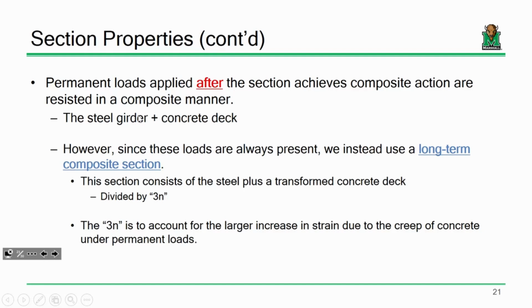Now, if you've had pre-stressed concrete, you know as well as I do that concrete is a material whose properties change over time. Concrete undergoes things like creep and shrinkage and what have you. And if you've had pre-stress, you've heard this stuff before. Well, because of that, concrete's properties not only change over time, but they get a little bit weaker, okay?